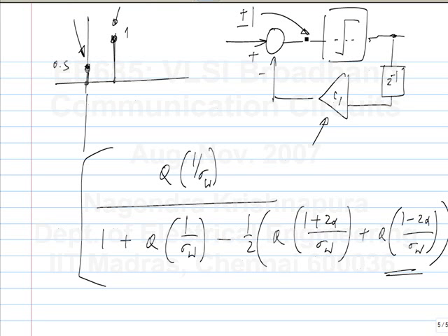See, if I want to normalize this to plus minus 1 and this is the response of the channel, what I need is a gain of 2 here, okay, so that this gets normalized to 1 and this C1 value is 2, okay. Now let's not worry about the DFE error propagation and all of that. Let's say it starts off with the right place and does it. So what is the problem with this system?